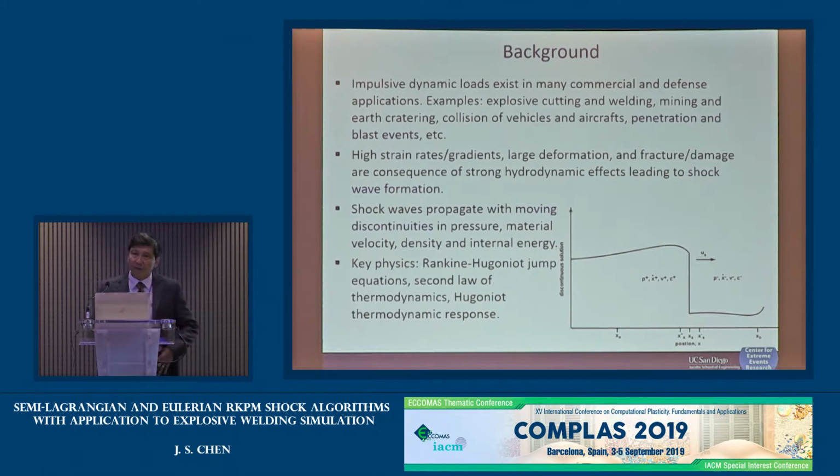But the key phenomenon in all these problems is shocks. And shocks really lead to very high strain rates, gradients, large deformation, fracture, and damage of material, as a consequence of very strong hydrodynamic effects. And a shock wave propagates with discontinuities in density, pressure, material velocity, and internal energy. So these discontinuities are propagating in space, similar to a fracture problem, but they propagate at a really fast speed.